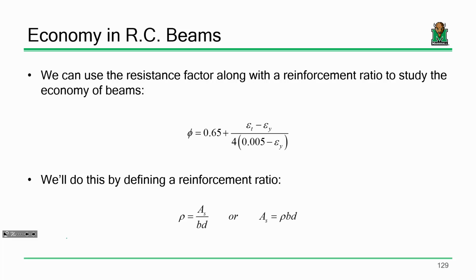We'll get to stuff like that later. To answer your question, that's a good question about box beams. Box beams are going to be treated more like T-beams because it's really not much different, because what you're really talking about is the analysis of a flanged section, because you have a really large flange and then a web. Okay? Now, what's the difference between a T-beam and a box beam?